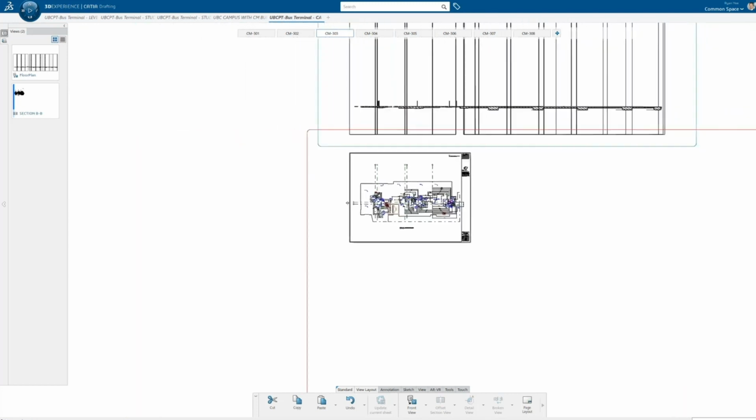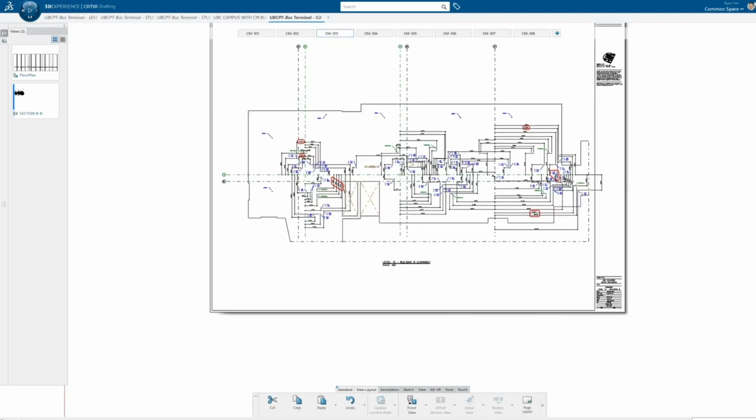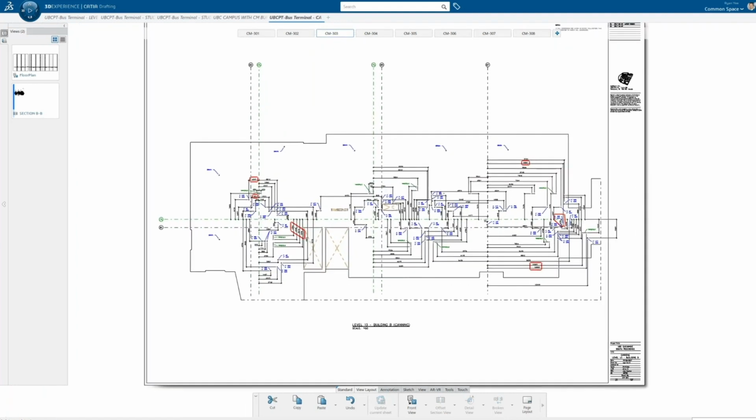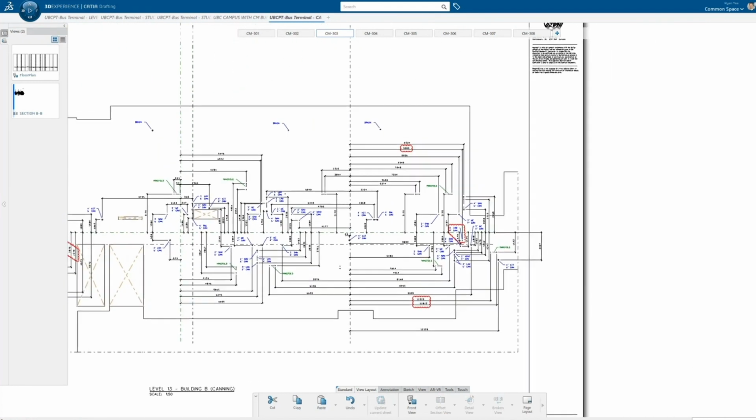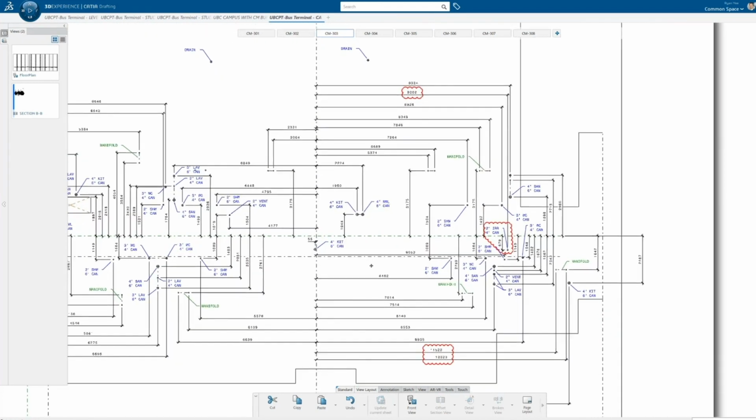After optimizing layouts and resolving issues, we produced slab edge, in-slab duct layout, and canning drawings for concrete detailing, sheet metal, and plumbing contractors. To maximize efficiency, we also produced inputs for the total station for canning layout.